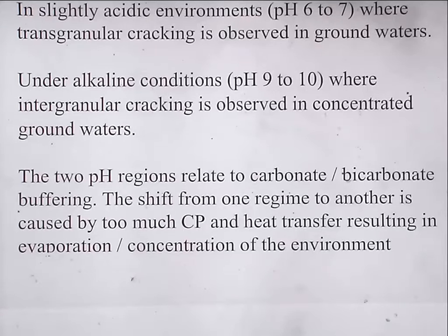a number of factors, and actually, what you're trying to do is get a balance between the formation of a passive oxide. So you've got to have some mechanism to get passivity into the material. In a steel, it has to be Fe3O4. So you've got to have the right environment to generate a passive oxide. You've got to have the correct balance between the rate of loading, the stress that's being applied, and the speed of the corrosion. So there's got to be a balance between the mechanical loading and the speed of corrosion, because